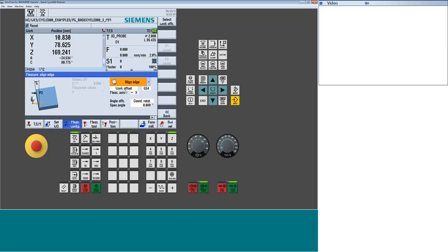So a lot of times I like to work from the minimum part being a 0, 0. So then I might find the center or whatnot. So line edge works very similar to a line plane. The only difference here is I can have a little more control, per se, telling it how I want it, what axis I want it to pick, what direction the probe's running in. Also, do I want to align the system based on the coordinate rotations? Those are the X, Y, and Z rotations around linear axes. Or do I want to rotate or set the axis specifically at a set rotary axis,